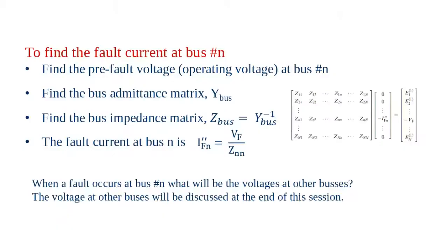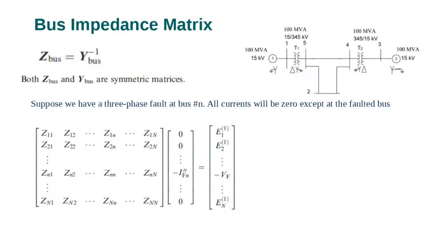And this is very simple here. You can see the fault current will simply be I fault equals V over Z Thevenin. Very simple. The pre-fault voltage over the Thevenin impedance gives you the fault current, which is this one here, as you can see. Okay, and that's why we draw the fault, and then we have the Thevenin impedance, and then we have the fault current.